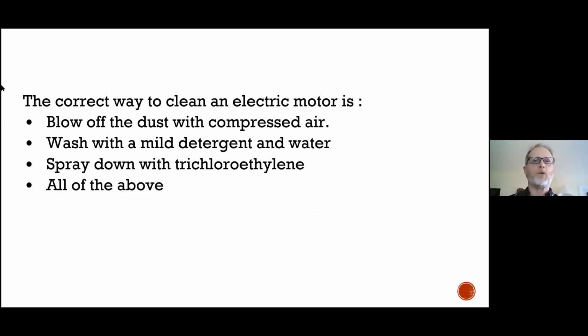A couple of quick review questions before we move on to pumps. The correct way to clean an electric motor. Basically what they're looking at is, again, the enemy of an electric motor is dust and high temperature. So we do not want to add water or soap. We're looking at just blowing off the dust with compressed air.